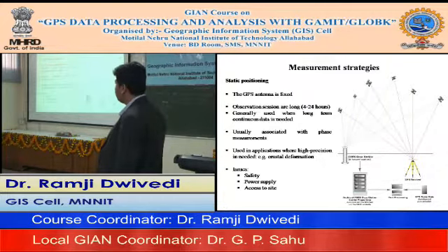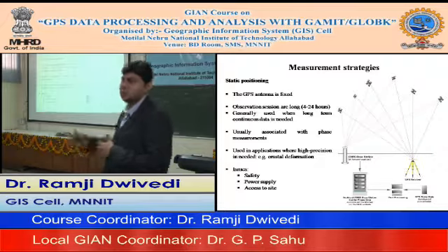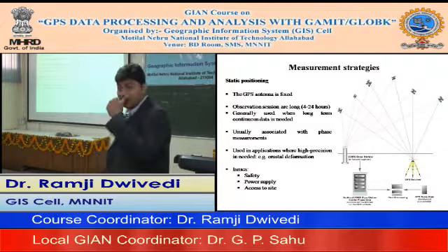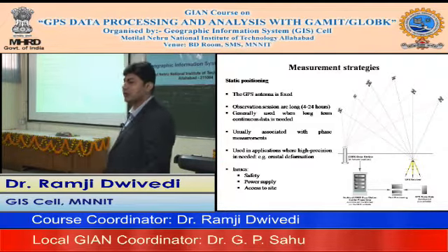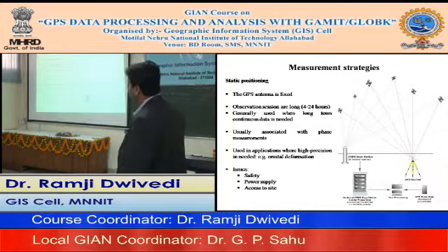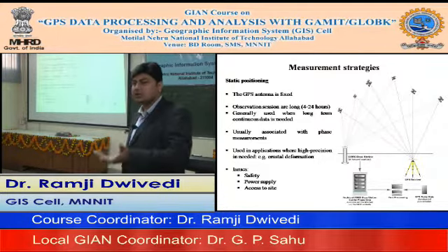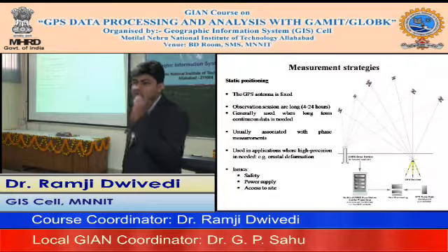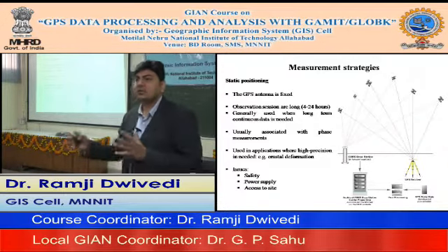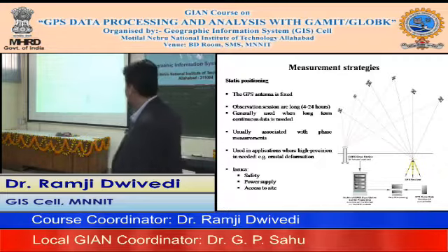Static positioning observation may be between 1 hour to 24 hours. So nowadays the RINEX files you are processing are 24 hours, so it's a fairly static mode. And this is actually used for what we call the application of crustal deformation. So those who are doing crustal deformation studies or reading the papers will have a network which has a certain data set of 24 hours.